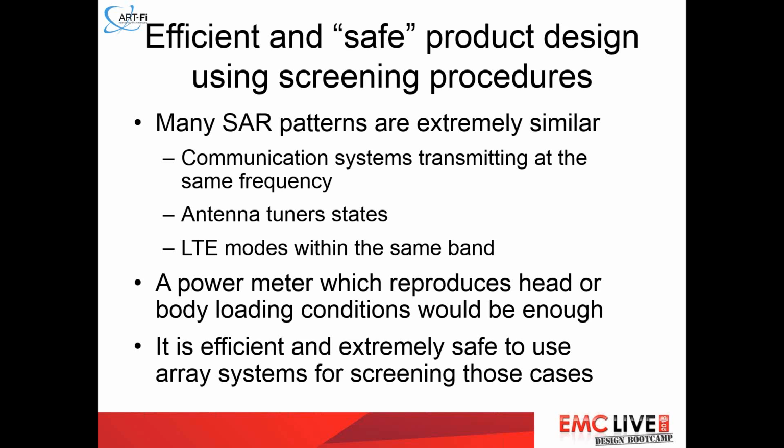So basically what you would need for testing those modes with SAR patterns that are extremely similar, or to rank them one compared to the other, is just a power meter that reproduces the head or body loading condition. That would be enough.